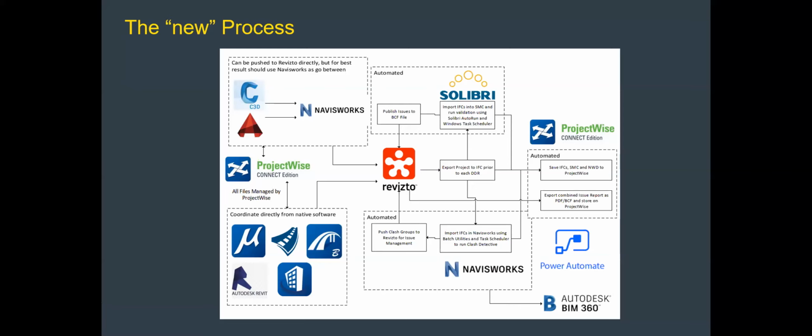For our Civil 3D and AutoCAD content, although there is a dedicated exporter from these packages, we like to create an NWC file and push to Navisworks, because this maintains more of the metadata in Revizto and then in the IFC later on.